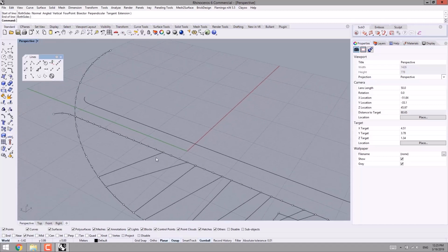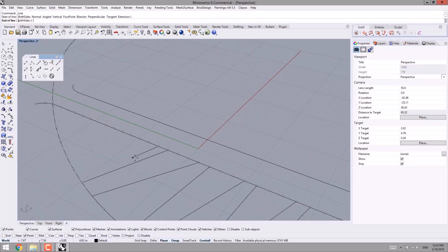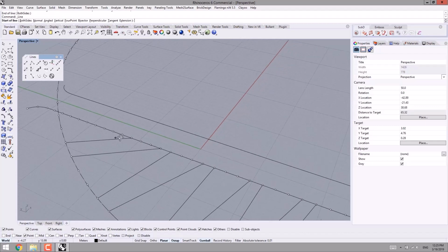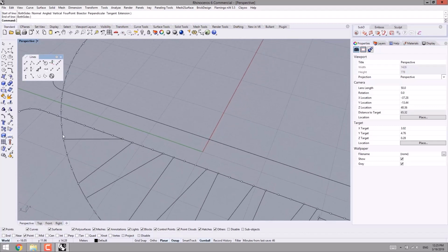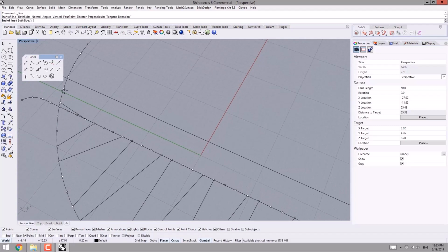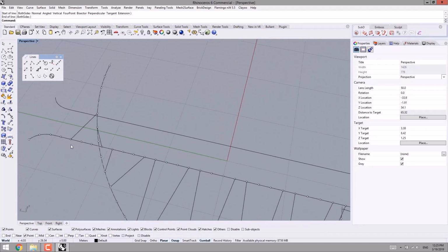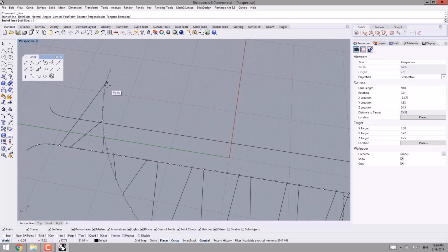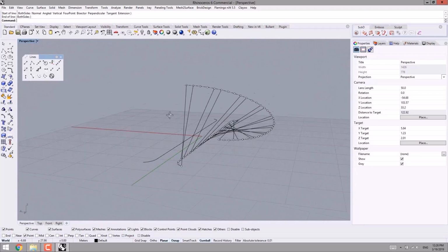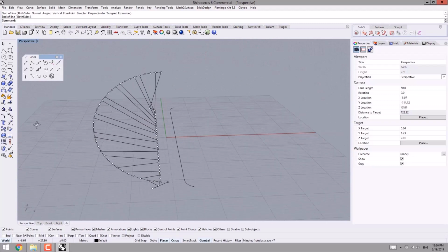Thanks for being patient. While you are connecting these points to each other, note that you should enable the object snap End points, since we should start our single lines exactly from the points. I keep on going. Wait for a second to complete the connections.